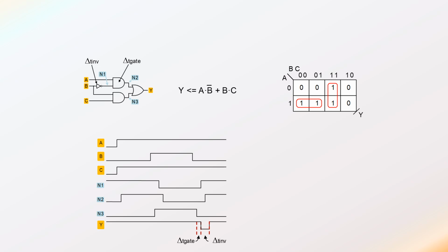And when those nodes are combined to drive Y, the output is an unwanted, maybe unexpected, short-term negative excursion on the output Y. And again, the duration of that short-term excursion is going to match the delay time through the inverter. So that's going to be a very small amount of time, but it's a non-zero amount of time.